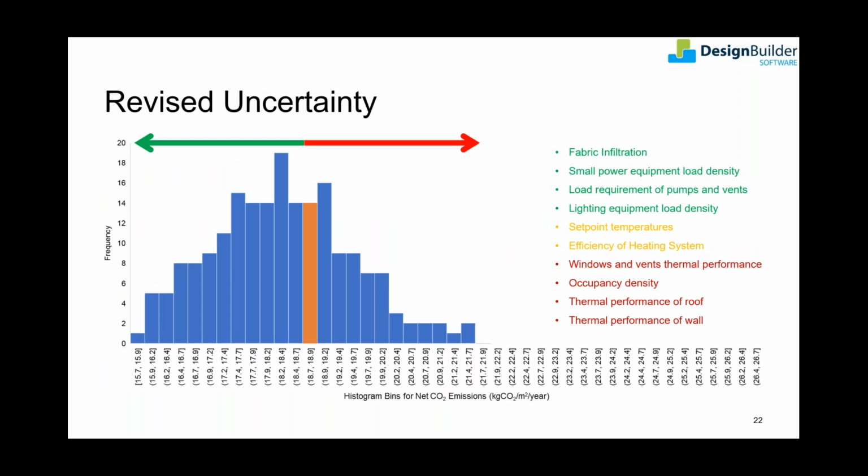Based on the feedback received from various uncertainty analyses, modifications were made in the project to have controls over load ratings of equipment and lighting being used, system specifications finalized and vetted at the design stage, separate vents with good sealing were installed, and provisions were made to implement soft measures for occupant education by the building owners. With a more robust commissioning and commitment to implement and preserve many energy efficiency measures, the probability of meeting the performance target was more than doubled, increased to more than 66%.